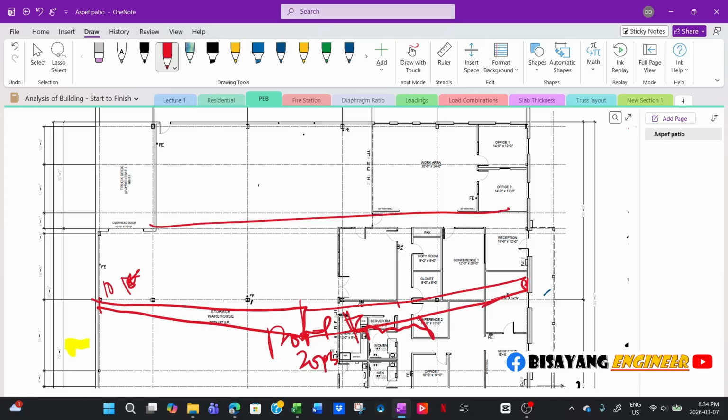You have to show the actual ponding load, so the truss manufacturer can include that in their calculation, in their design of the joist.